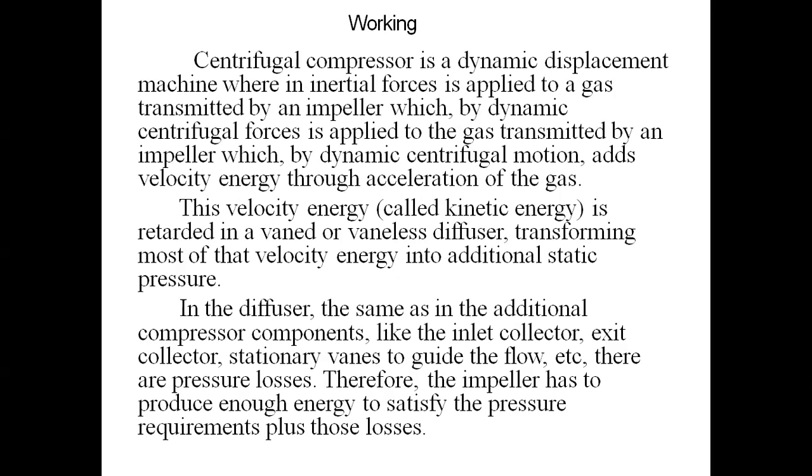A centrifugal compressor is a dynamic displacement machine where inertia force is applied to the gas by an impeller, which by dynamic centrifugal motion adds velocity energy through acceleration of the gas. This velocity energy is retarded in a vane or vaneless diffuser, transforming most of that velocity energy into additional static pressure.